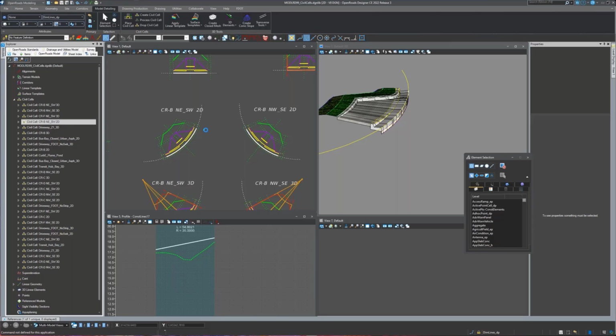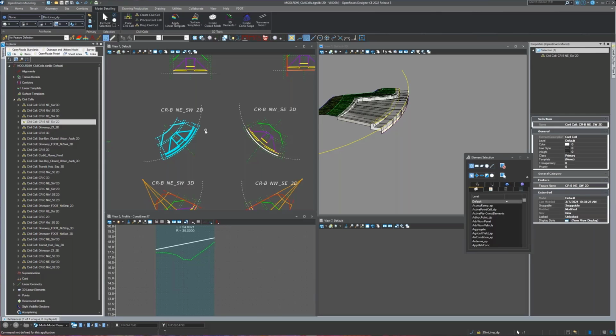So when I created that civil cell, there it goes. We have our references in here, and it basically just calls the reference whatever the feature definition name is. So when somebody goes to place the civil cell, it's going to ask for construction lines white dash.